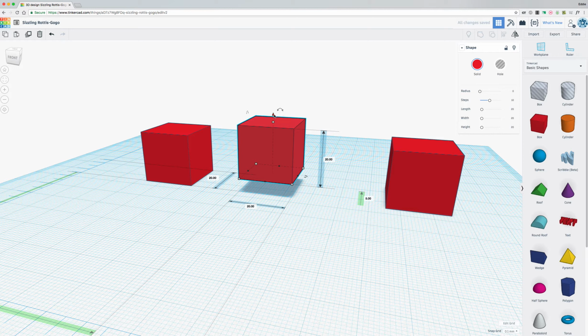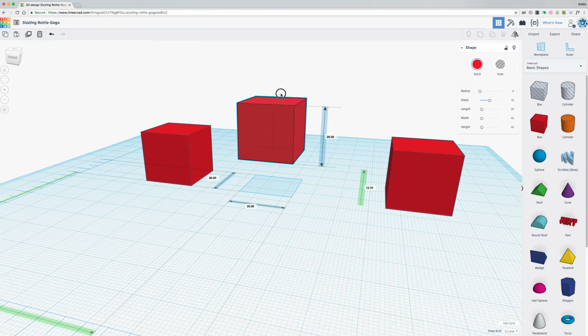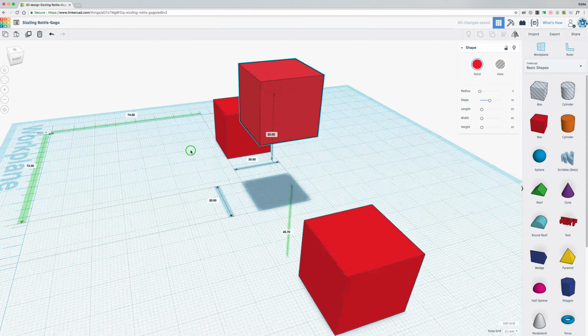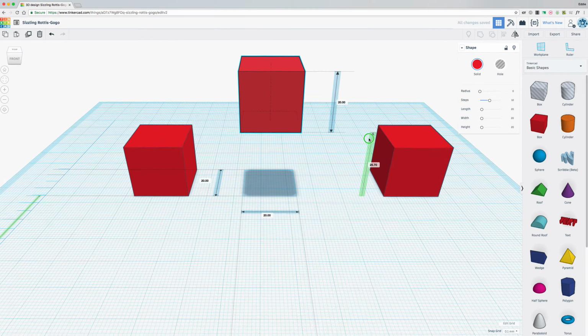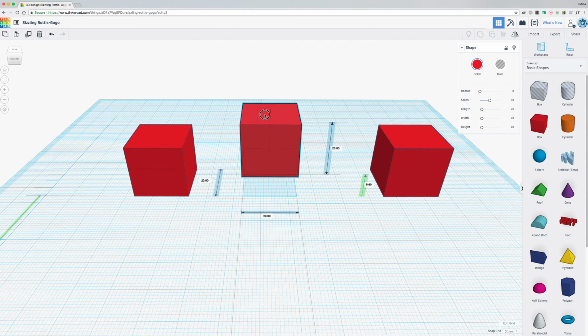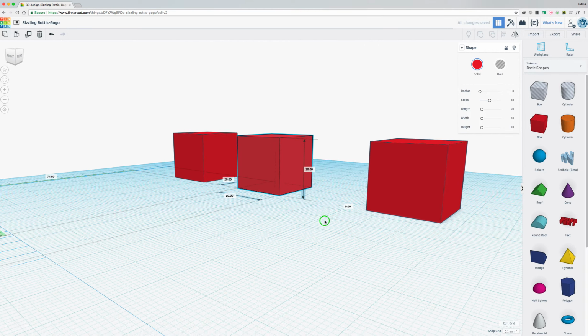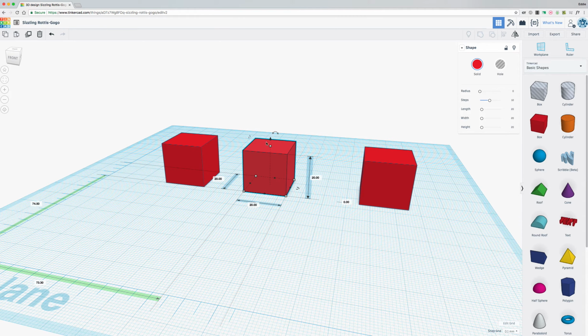Or you can go to the cone, let me go back to 0, and left click on the cone when it turns red and hold your mouse and move it up and move it down. This lets you raise objects if you're building in three-dimensional space and you need to take your object and put it in the air. So I'm going to go ahead and hit that back to 0, and the object is now at 0. So that is how you use the cone.